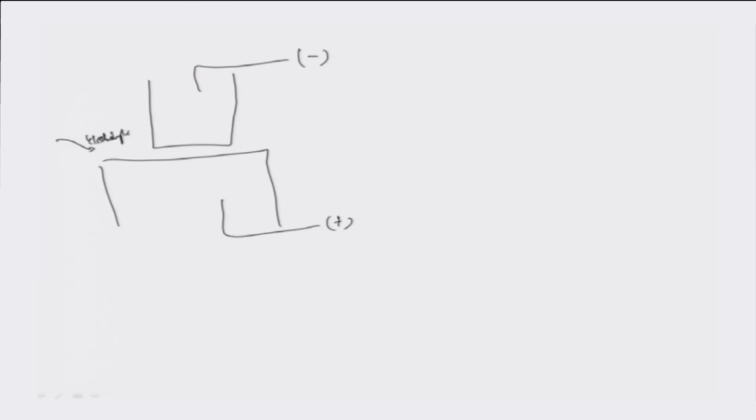And for that I would like to just illustrate that if this is the electrode, supposing in an ECM operation, and there is a workpiece here, close to it, and the electrode, as you know, is made the cathode and the workpiece is made the anode, and supposing there is an electrolyte instead of a dielectric fluid which comes into this region, which starts the gasification process. So, there are some gas bubbles which are generated close to both the workpieces, as a result of which there is a gas film which develops between the anode and the cathode.